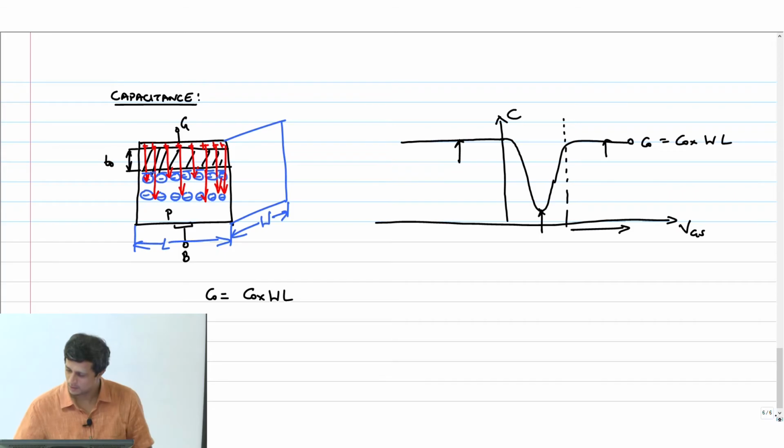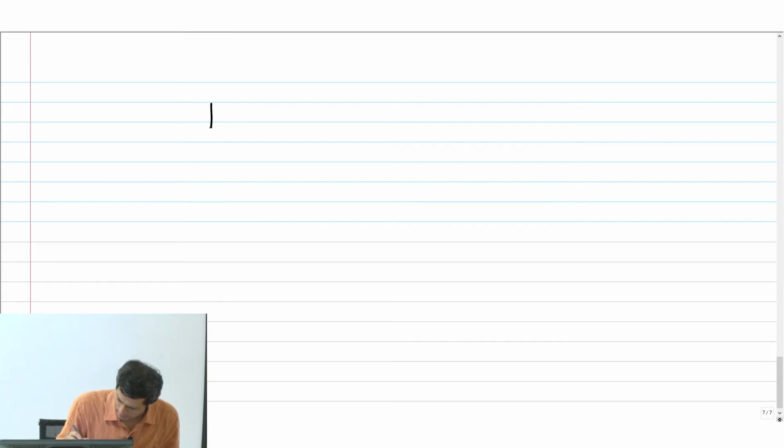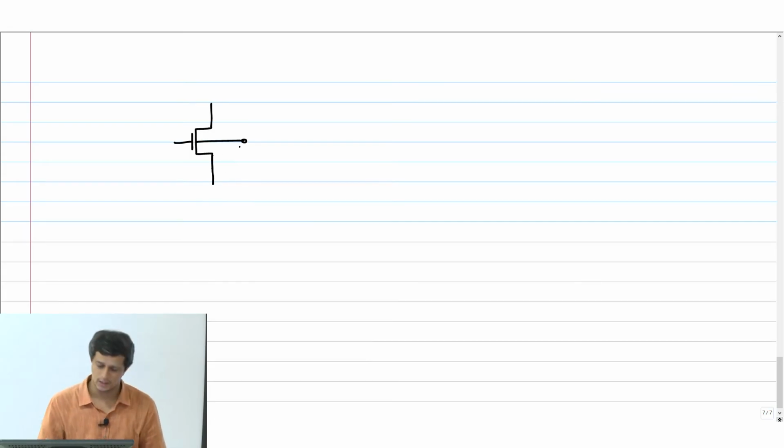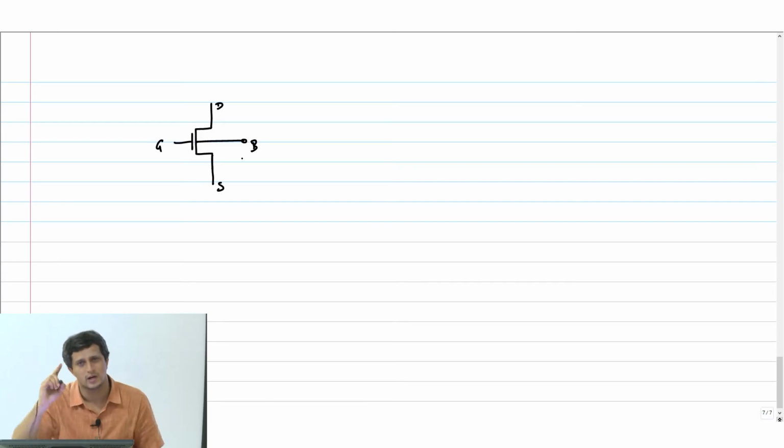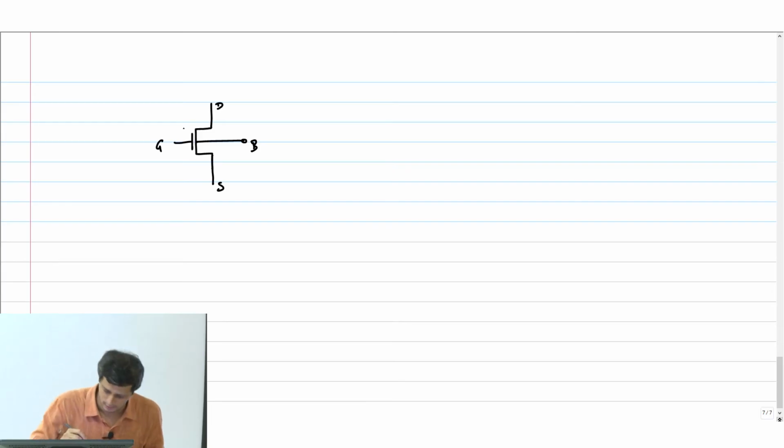Okay. So with that, I can move into the picture of the capacitance for an NMOS transistor or a PMOS transistor actually. It's a 4-terminal device. It turns out there are capacitances all over, from all these terminals. This is gate, drain, source, body. Without loss of generality, I am just saying one is drain, other is source.